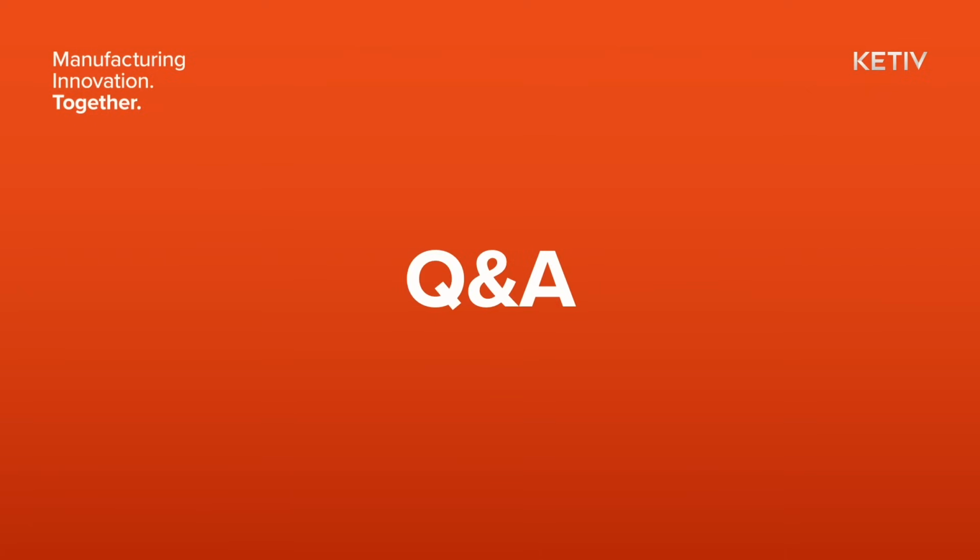So Kevin's asking another question. Does Plant do BOM, bill of materials? Yes. So Kevin, specifically with leveraging creating your own catalog content, once you actually build your model, you can then run automatic isometrics off of them where it's going to spit out a bill of material within those ISOs. And these ISOs aren't 3D ISOs, they're just 2D line isometrics, but it is going to generate a full bill of material based off the information I laid out within my catalog.